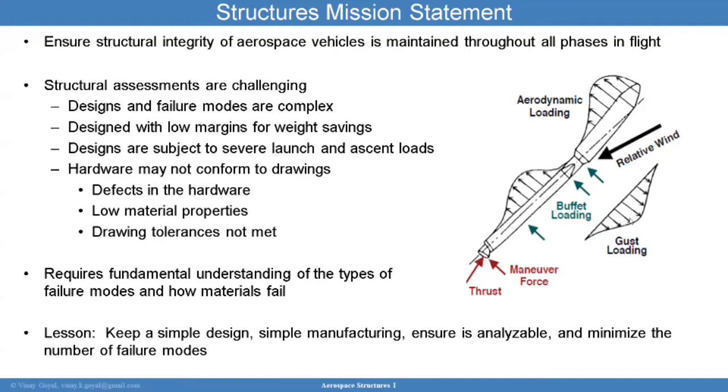That way I probably can accept that damage without having to redesign, having to repair, and so forth. But you don't want to keep too much margin to the point that your structure is too heavy, and therefore you're unable to fly the part because it's too heavy, right? We don't want that situation.